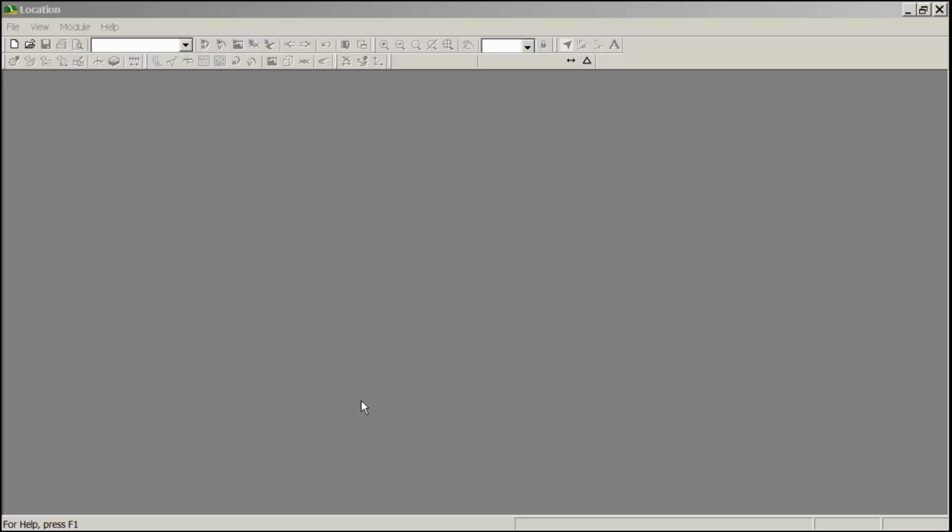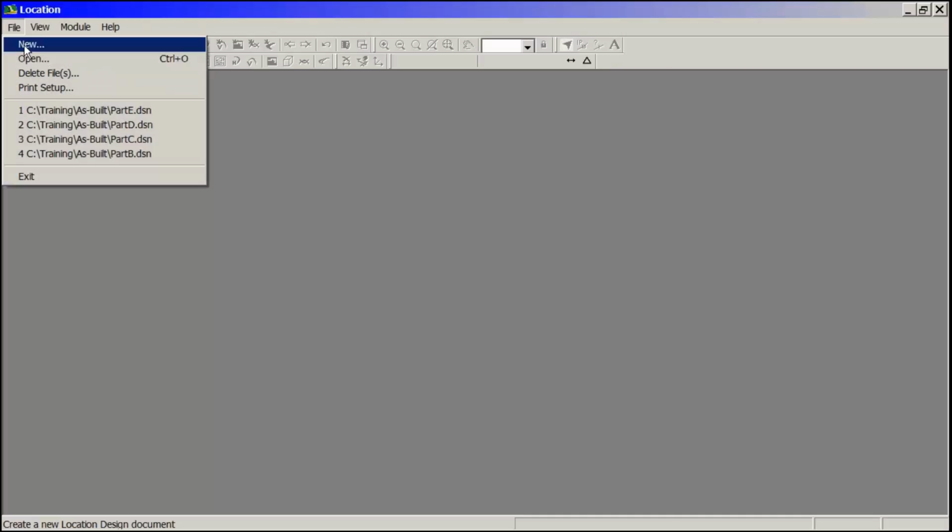Today I want to show you how to do calculation of as-built quantities. What as-built quantity calculation entails is bringing in three separate surfaces. You could have more. First of all, I'm going to bring in the topo, the original ground, then a stripped surface, and finally a subgrade surface. I'm going to compare the volumes between the surfaces.